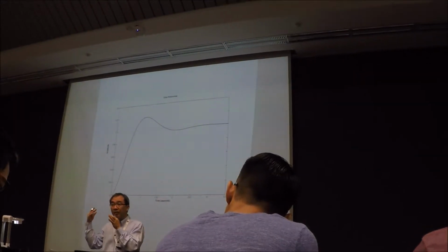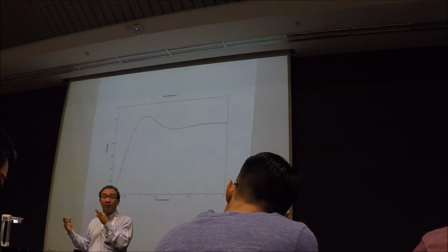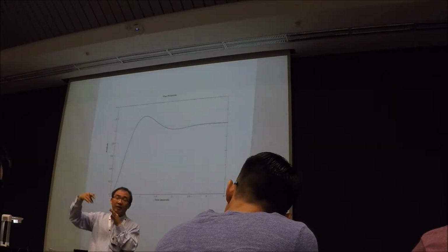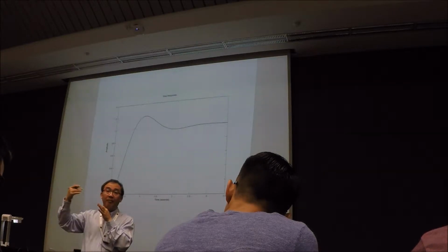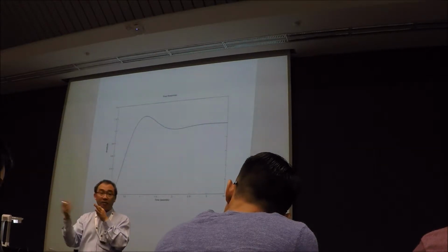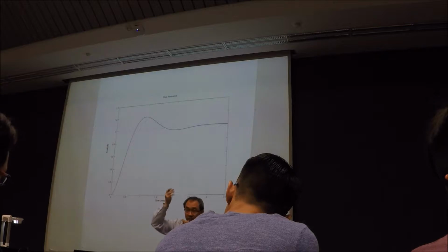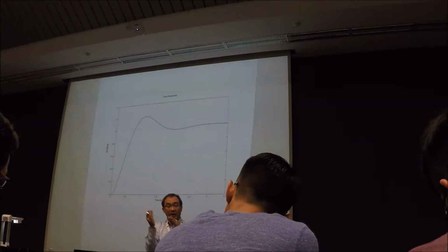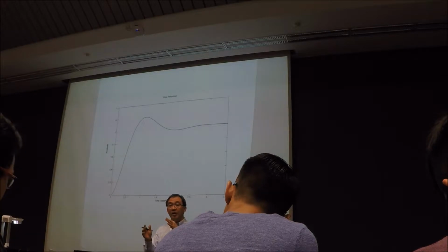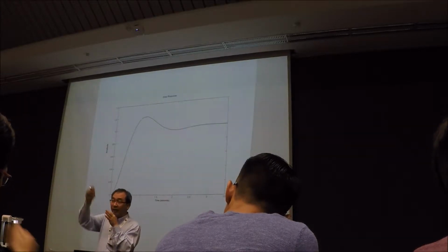And that is important because when you place a zero into your closed loop system, you need to be careful with the overshoot, depending upon the zero location relative to your complex conjugate poles. If you have complex conjugate poles, that means you have an underdamped system, and the zero will aggravate the effect of overshoot, but at the same time, the zero actually speeds up the response. The downside, of course, is that overshoot becomes very high. The good thing is the response becomes faster. And as we have discussed so far, we also conclude that this only affects the transient, because the derivative control action is only effective during the transient.